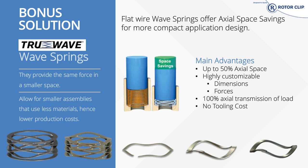Wave springs have an almost infinite number of designs with different dimensions and forces, and once we have a wire size, there's no tooling, as tooling is all matched to the wire. So we make our designs to match the tooling we have, so that we can offer you a low cost and even low volume, if necessary, part without additional costs for tooling.